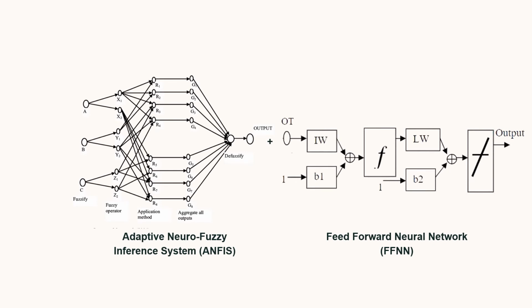The distribution system uses 3-phase electric power, usually called phase A, phase B, and phase C. Thus, the multiple inputs for the ANFIS are the fault currents for each phase, which are IA, IB, and IC. Fault current occurs when a fault happens at the feeders or lateral lines. Then the output of ANFIS will be in terms of binary 1s and 0s.